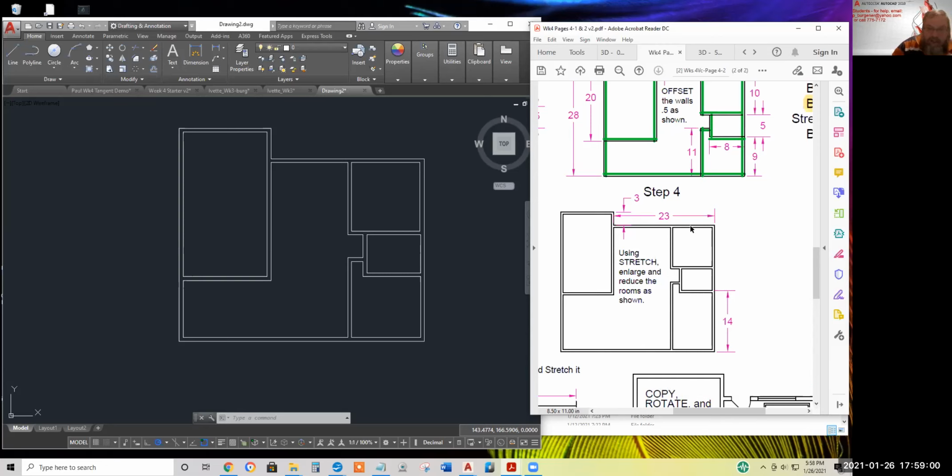And the stretch command will not only move these interior walls 3 units to the right, but it'll lengthen what we cross with a typical AutoCAD crossing window or polygon or lasso, I think. This is another concept that students have trouble with. They don't draw the crossing window big enough, or they forget and draw a regular window, or there's a few other ways you can mess it up.